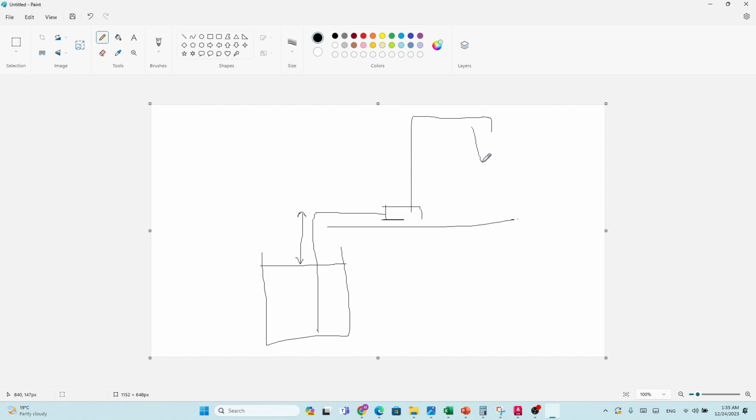Okay, let's suppose you have an underground tank. In most cases, the pump is installed at the surface. So this is the suction head, this is the water level. The water needs to be sucked up to the center line of the pump, and this is the discharge head. So overall, the static head is like this. This is the total static head. Okay.